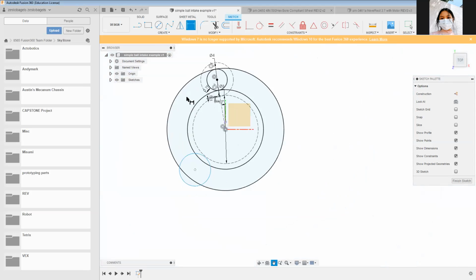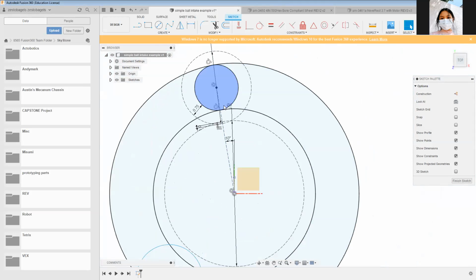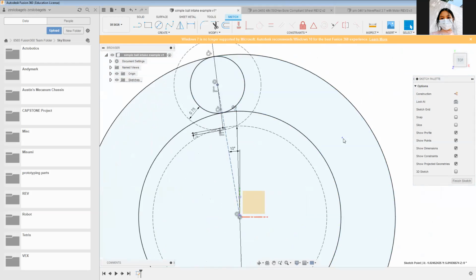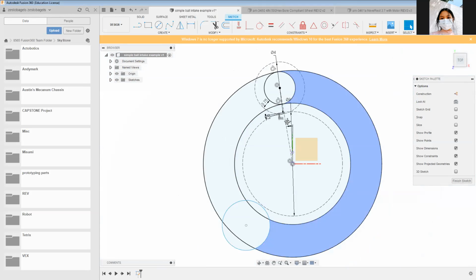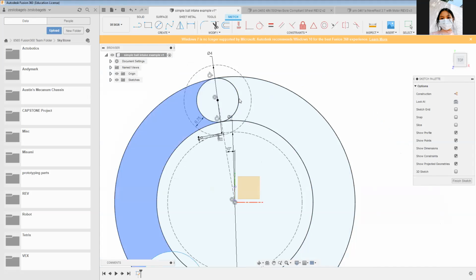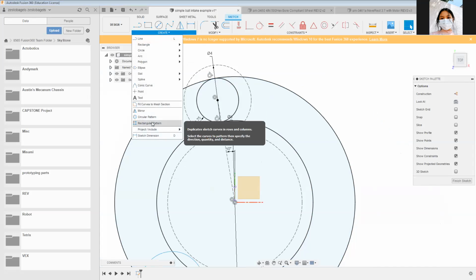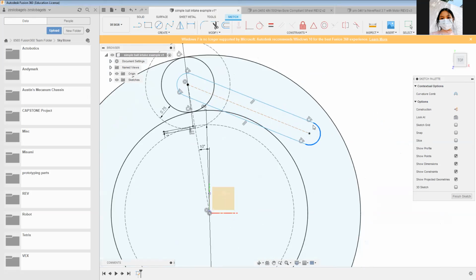Next, we probably have to put the motor somewhere. So the motors, you probably want to put them towards the back if this is an intake that's going to be all moving and stuff, because then the motors define where the center of gravity is, and we don't want to have to move the motors whenever we move the intake. So I'm just going to do a 1-stage belt pass. So I'm going to do a slot tool, which is pretty helpful for this. And now we have the basic path.